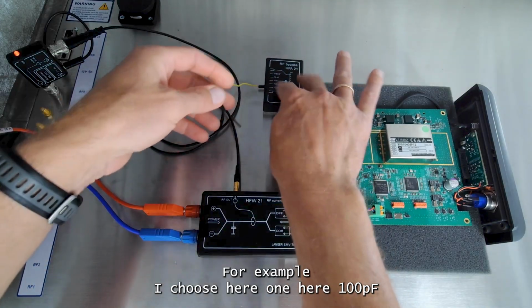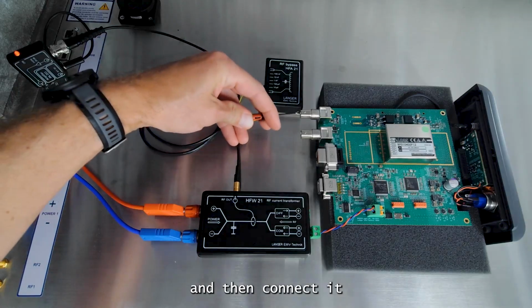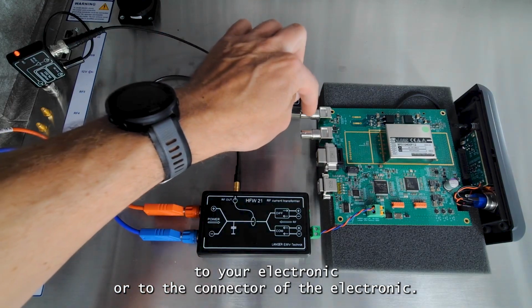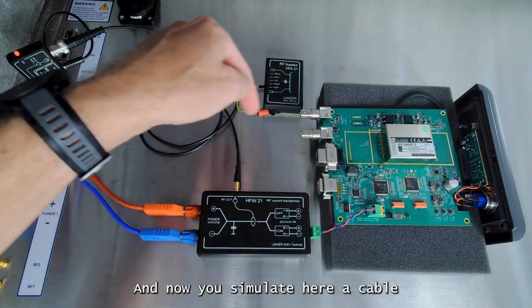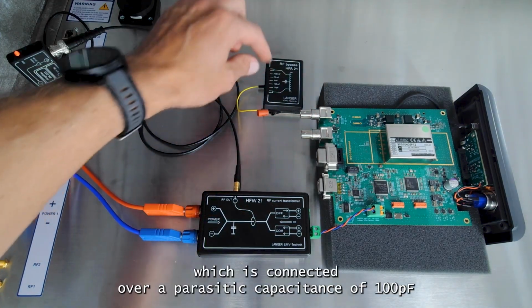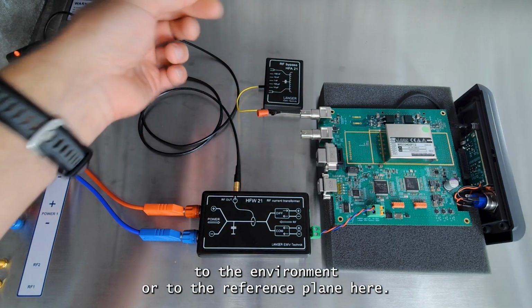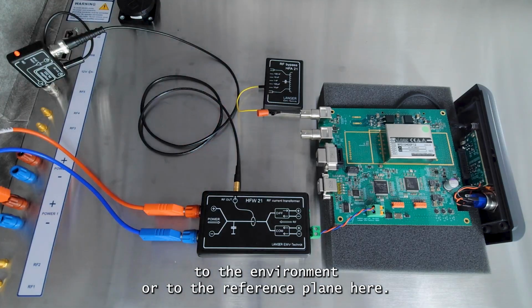For example, I choose here 100 picofarad and then connect it to the connector of the electronic. And now you simulate a cable which is connected over a parasitic capacitance of 100 picofarad to the environment, to the reference plane.